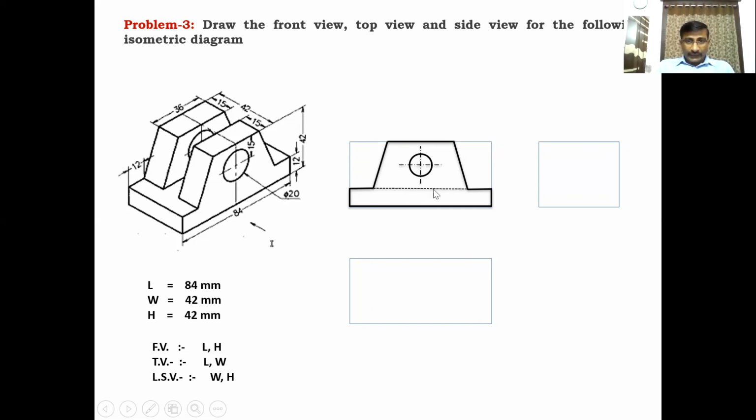Okay, and another dotted line is there here. Which one is the invisible line here? This line is there, no? This line from this point to this point is invisible from the front side. This must be drawn with a dotted line. Okay, that is an invisible line. When looking from the front side, the line which is passing through this corner is invisible. So that's why I'm drawing a dotted line here, an invisible line. Clear? Coming to the top view, I draw the top view.